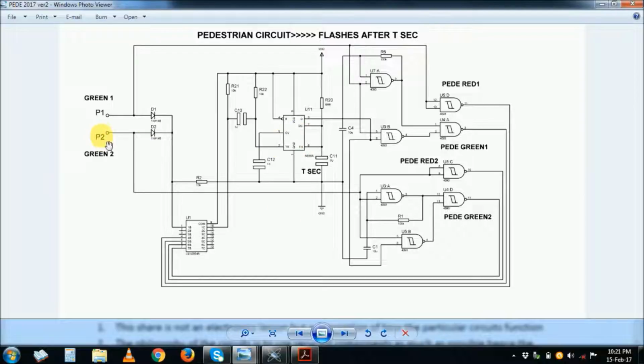So you have your green signals from the manual control board, the P1 and the P2, coming here, connected here, and then you have your outputs for relays to operate using this relay driver. But this driver is also used to strobe the timer. So you have 4 driving relays, but also using the strobe, and then the timer, and then our NAND gates here, 2 ICs, 4 NAND gates in each IC. So we have actually 2 logic ICs.